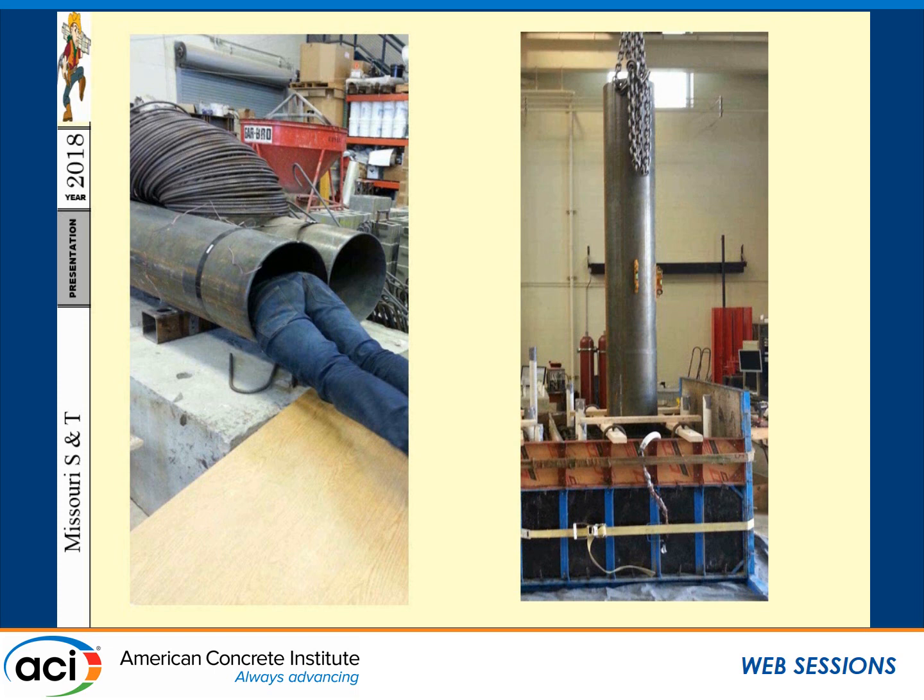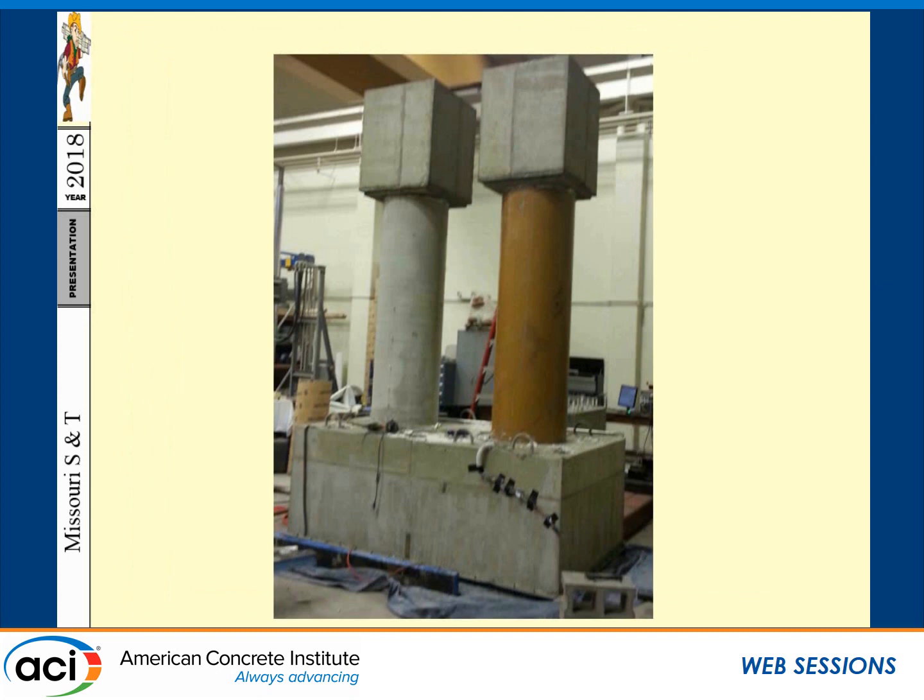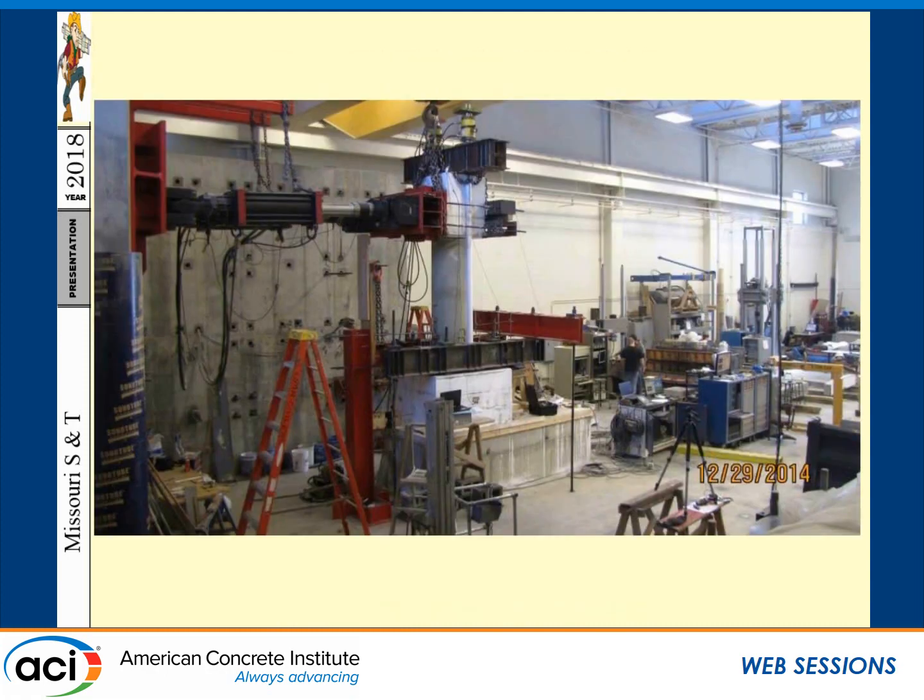The other scenario that we did is to have the column as precast and use a socket connection to insert the steel pipe into the footing. So we tried both of them. So here are the columns. There is a separation over here. It's not clear in the pictures, but it's not a bent. These are two different columns on two separate footings. The one to the left here is the conventional reinforced concrete. The one over here is the one with the glass fiber.